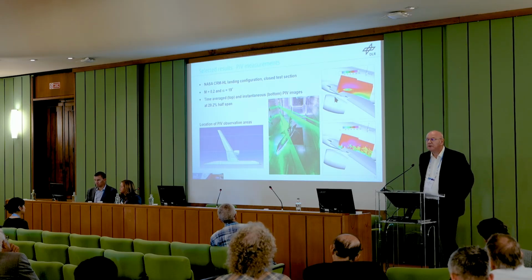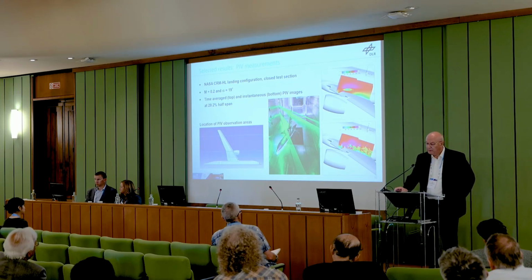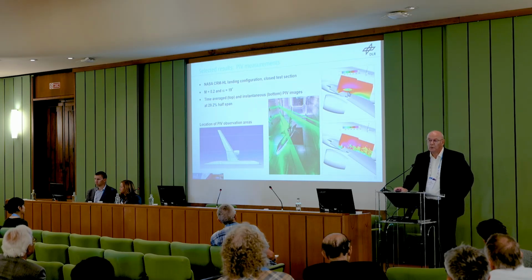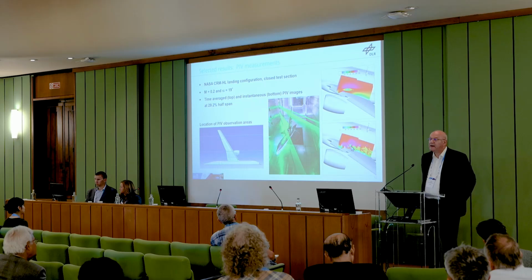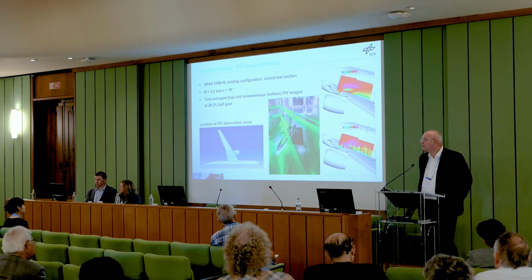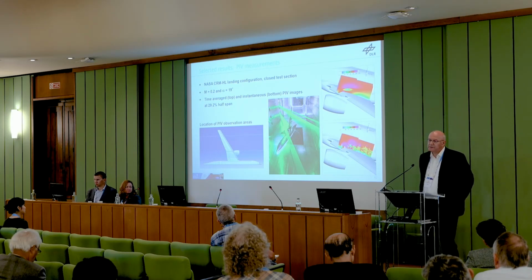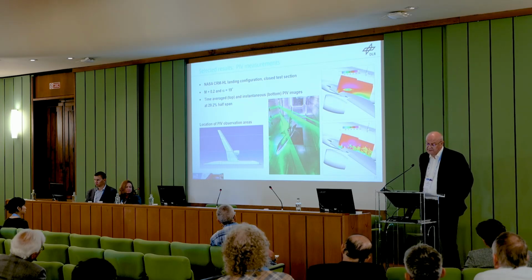The first one is a time-averaged velocity field, U component, high velocities in red, low velocities in green and blue. What you see if you look at that is specifically here the low speed area, this green dot, which corresponds to the nacelle strake wake cutting the slice. Down on the bottom, we have instantaneous velocity information, which gives you an idea of the turbulent structures that we find here. And the idea is, with this time-resolved PIV, to provide data that are suitable to derive Reynolds stresses, so we can compare the scale-resolving computations that we do to the PIV measurements in terms of Reynolds stress.